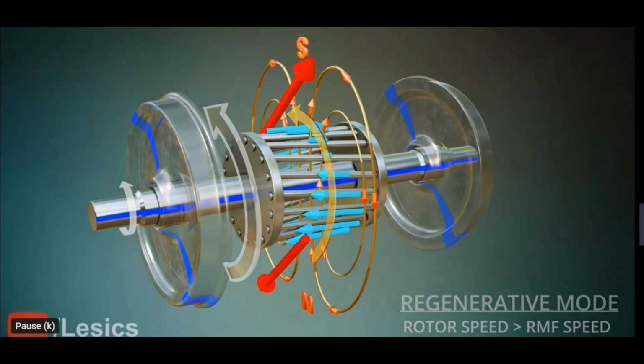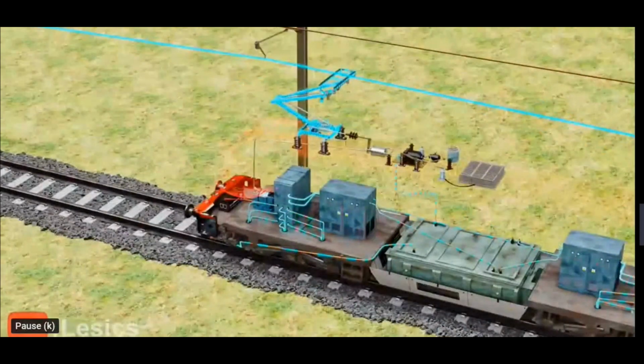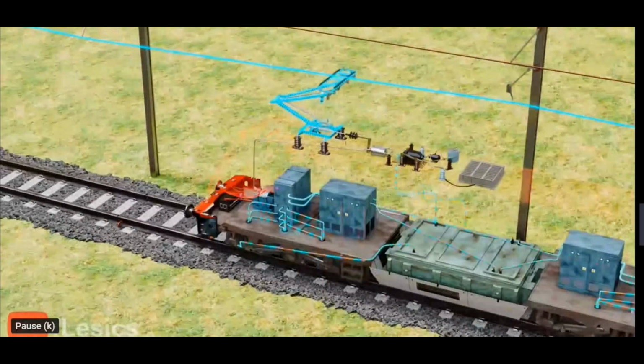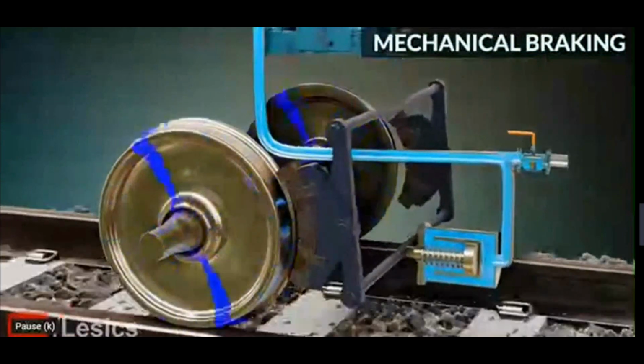However, this braking method can't stop the train dead in its tracks because regenerative braking doesn't work at low speed, which means it can slow the train down. But after that, you have to apply the pneumatic brakes to stop the train completely. This is a different kind of mechanical brake.